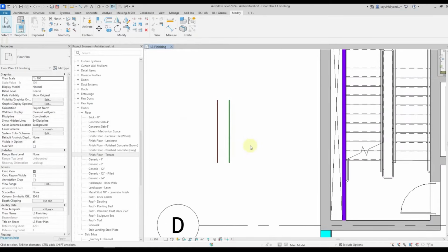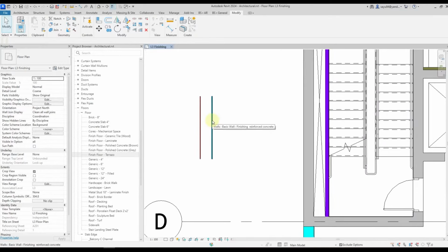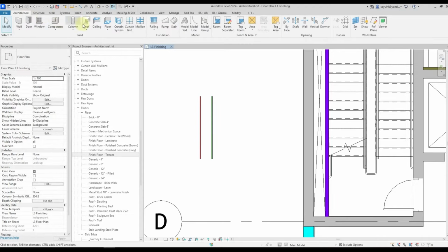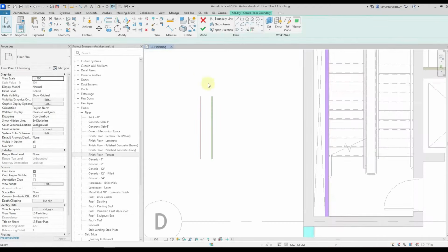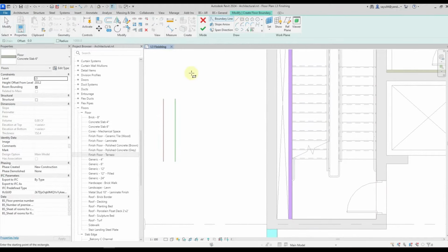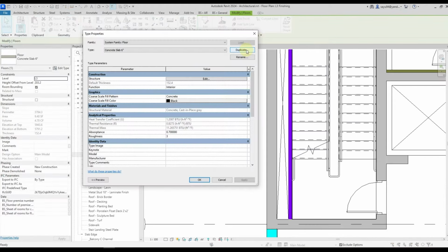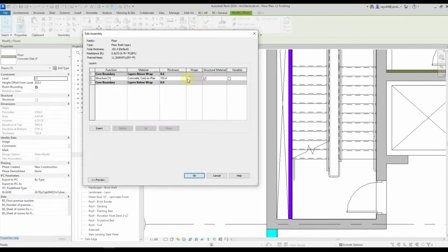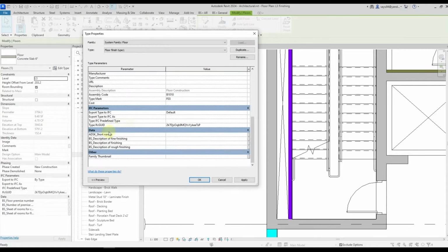Now let's do the same thing for finishing types of floors and ceilings. I'll take the slab tool, model it in small fragments and create a new type. Let it be the floor finish type 1. Click OK. Here we set the material and the thickness will be 50mm.